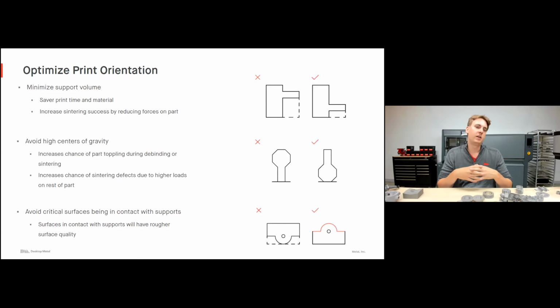Avoid high centers of gravity. High centers of gravity increase the chance of your part toppling during debinding or sintering.